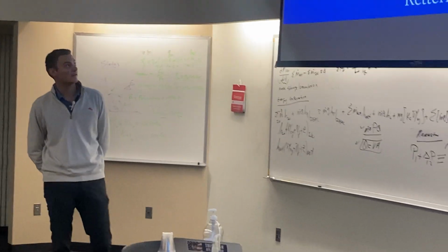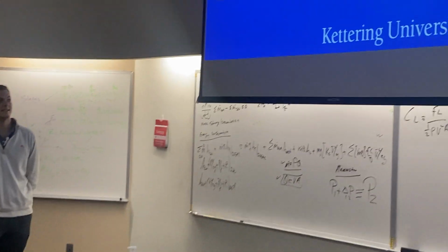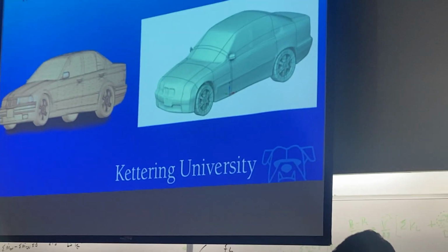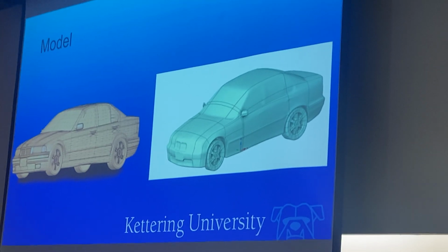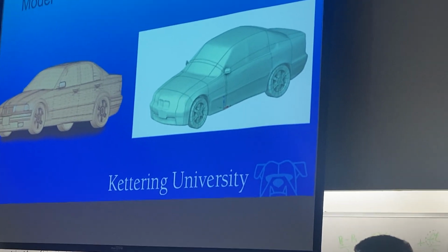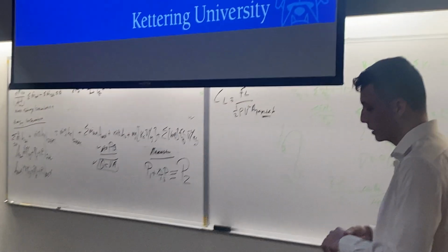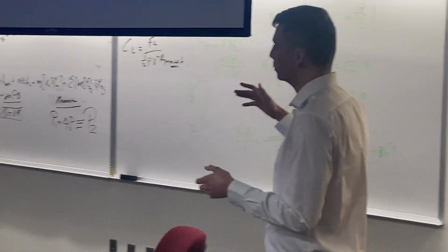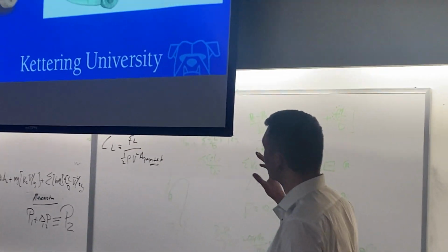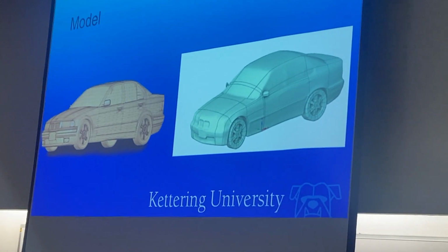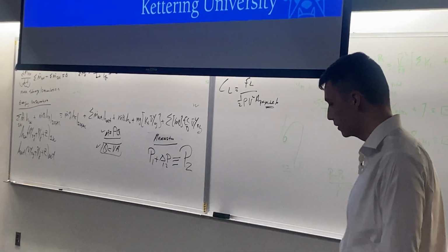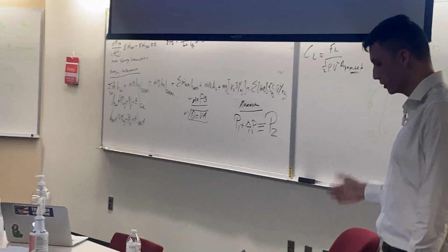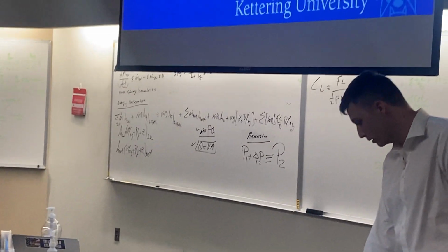So this is the model. It's a 3D scan of a 1995 BMW 3 Series. It's a very common car and used a lot in racing, so that's what we're using. Yeah, and one thing to note is that because of the file nature, we had to shrink wrap the body, so it looks a little bit smoother. So that's maybe one limitation of the realities of CFD, is you have to make some assumptions and smooth things out a little bit.